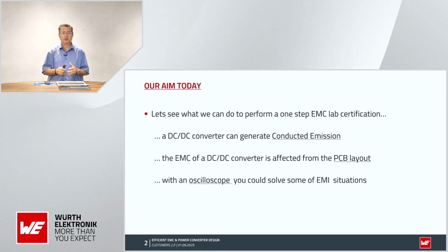First of all, we have to perform a very good PCB layout. The most important design tip is, when you are designing something, take care of your grounding. You must have a good grounding. You can put tons of ferrites and tons of capacitors inside, but if you have a bad PCB layout with a bad ground, no component will help.